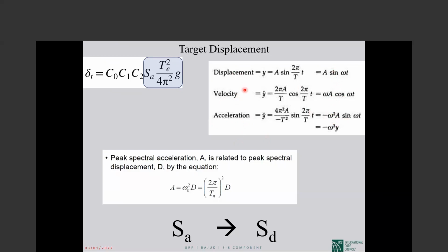So interesting. So if you have the response spectrum curve, you easily can calculate the maximum acceleration of this building. But if you want the displacement, divide it by omega squared. If you have the maximum velocity, divided by omega gives you maximum displacement. Multiply by omega gives you maximum acceleration. So nice, so easy.